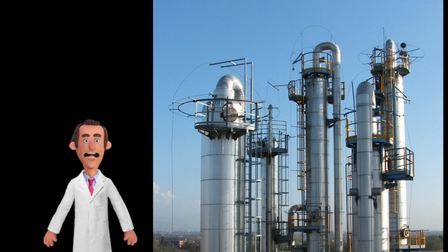To make the results more practical and accessible, I developed a MATLAB App Designer tool that allows users to select different operating conditions and instantly view the corresponding condenser duty, reboiler duty, total duty, energy savings, CO2 reduction, carbon credits, and estimated carbon credit value. The analysis showed that optimizing distillation column operation not only reduces energy consumption and emissions, but can also provide potential annual financial benefits through carbon credit generation.